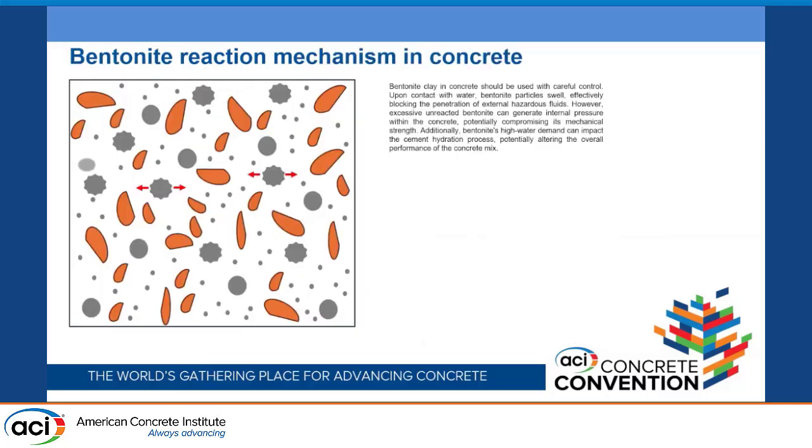Bentonite reaction mechanism in concrete. We believe that bentonite clay can be beneficial in concrete, especially in regions, for example the Midwest, where there is a problem of salts, especially in winter. But the dosage should be controlled, as the dosage of bentonite clay increases, it adversely affects the overall performance of the concrete.